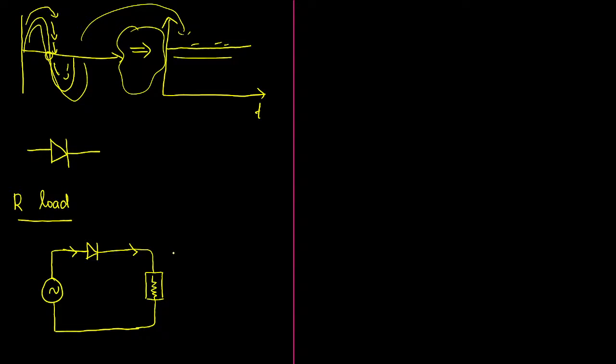So the moment you close this switch, where are we going to keep the switch? Let me create an arrangement here. This is the point where I had a break. Now I am simply closing it. When we close it, what will happen? The diode will be short circuited. Basically, treat this diode as an ideal one. I haven't kept any voltage drop, and I don't want to, because that voltage drop is very small, so I'm neglecting it.